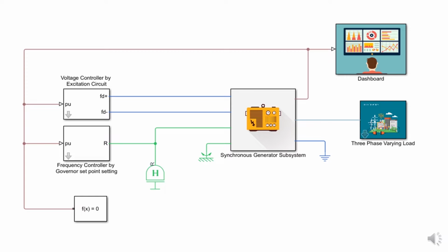We will model the time variable load as a typical power consumption system, which has a characteristic load profile with time. As demands of power consumption changes over the course of a day, the generator must be capable of regulating its operating parameters in response to those changes. Otherwise, this can destabilize the particular power system.